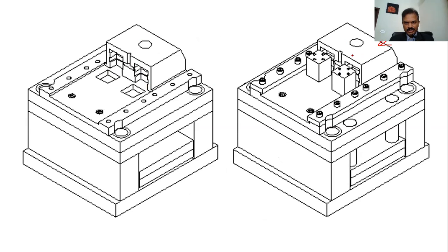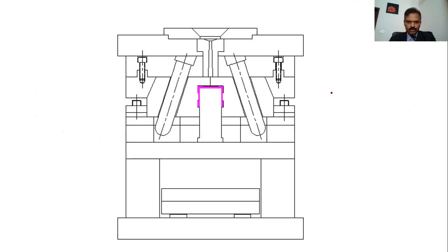And what is going to make the movement in and out is the finger cam hole, which is cut at an angle. When the finger cam goes up, it will push the slide out, right? And vice versa. When it comes in, it will push the slide in. So this is the arrangement on the bottom side. So this is how the sectional view will look.